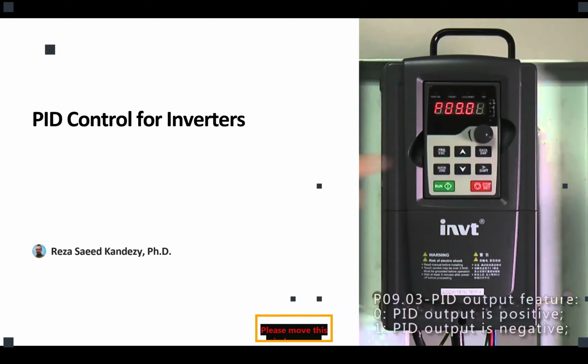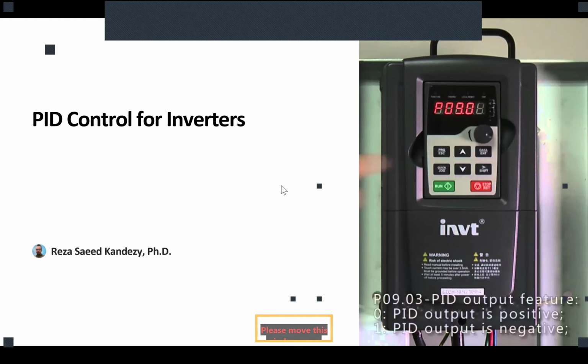We talked about the PLL, and we talked about the PID control system. We said the PLL tries to synchronize the inverters with the grid and make sure that we don't have deviation over the frequency, and PID control tries to answer the demands of the grid. So if there is a voltage change or a current change, meaning there's a load change, we could address that, and basically our inverter could supply that demand from the grid. Are we clear so far?